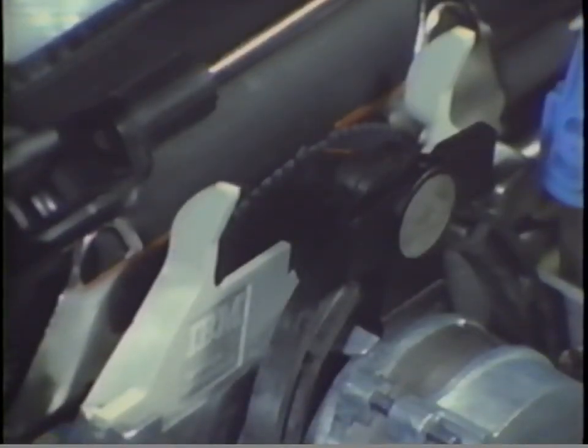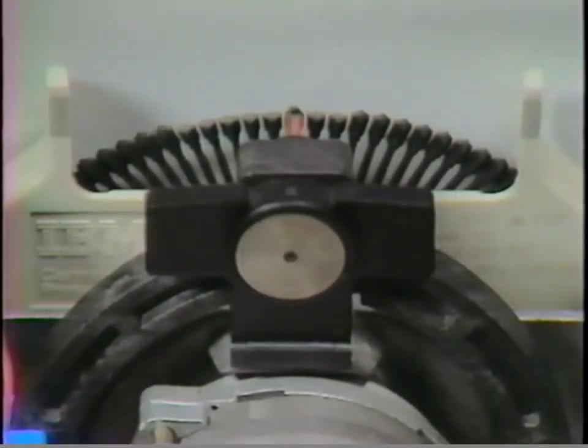The printer board does 5 things during POST that involve selection. The first thing the printer board does is to spin the selection motor to ensure that the selection motor hub is engaged with the print wheel. The second action of the printer board is to home the print wheel. The third and fourth actions are to electronically sense the pitch and impression level of the print wheel. Finally, the printer board lightly fires the hammer solenoid. When power-on reset is complete, the print wheel is detented in the home position. Now let's watch the POR again at normal speed.